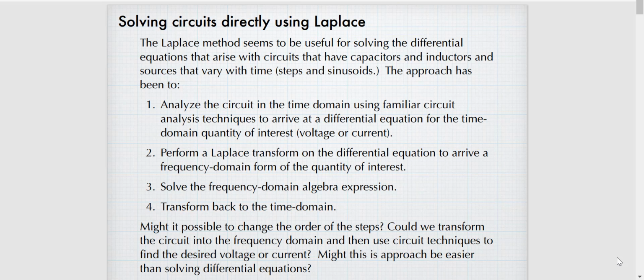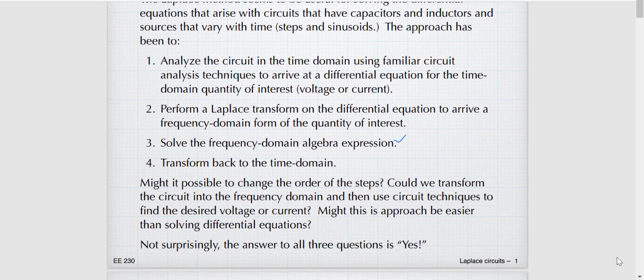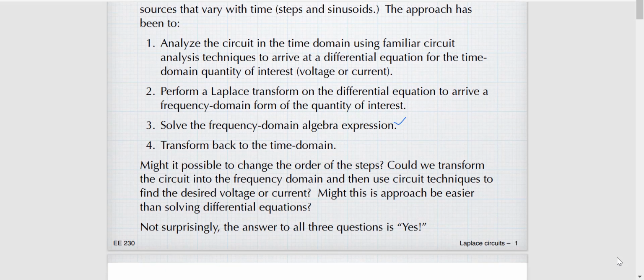And then after we get the equation in the time domain, we have to perform the Laplace transform. I mean that we transfer the equation from the time domain to the S domain, and then we solve the frequency domain algebra expression in the S domain, and then we transform back to the time domain.